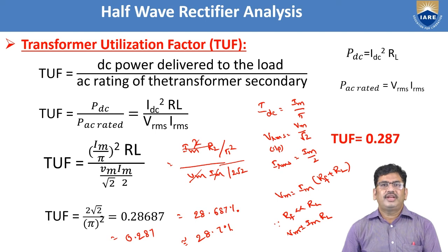The objective of the rectifier is, for many peripherals or electronic gadgets, we require a DC source. So the AC source which we are getting for households, we need to convert into DC source. For that purpose, we are using rectifiers. So the various rectifiers existing are half-wave rectifier, full-wave rectifier with a center-tap transformer, and full-wave rectifier with bridge circuit.